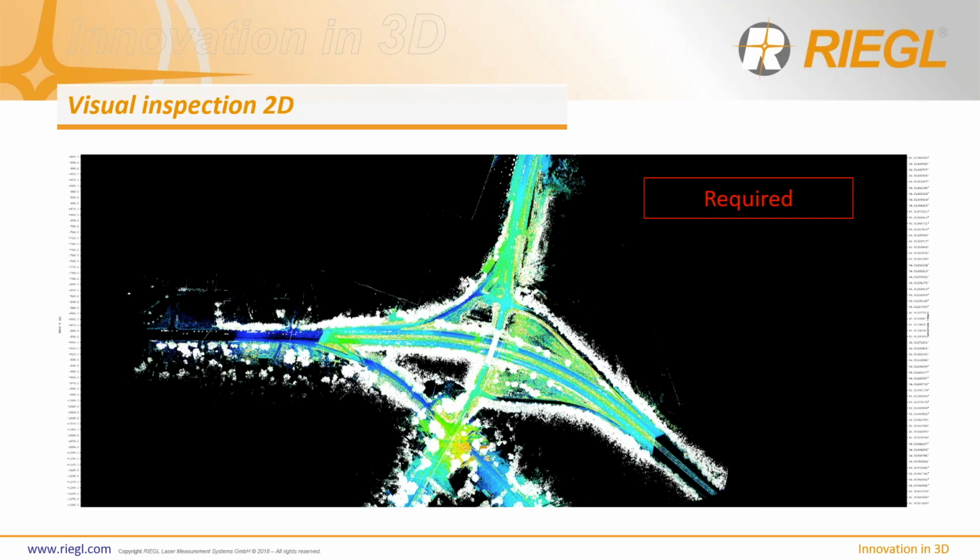So what you do is you go into your 2D view, you load all your records, and this is scaled height difference. The scaled height difference is showing you the absolute value, the difference between the lowest point and the highest point in the point cloud. So if you have 10, 15, 30 passes in here, you're going to have some variations between each pass. That's to be expected.